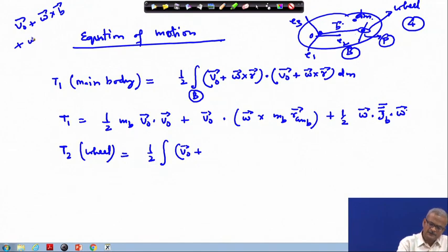So for that, if omega_w is the angular velocity of the wheel in the inertial frame, which we are writing as the absolute angular velocity as per our earlier notation, and rho is any point, we need to write it like this. The same thing can also be written as the velocity of the center of mass of the wheel plus omega_w cross rho.